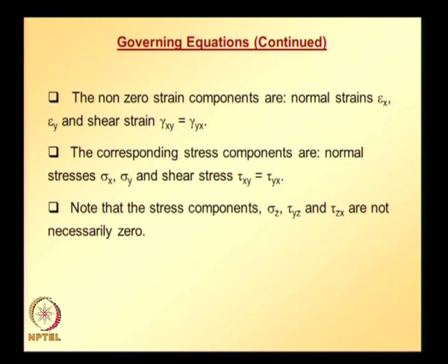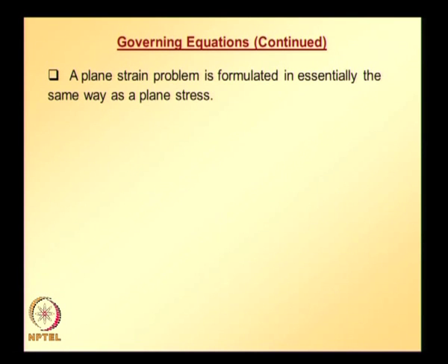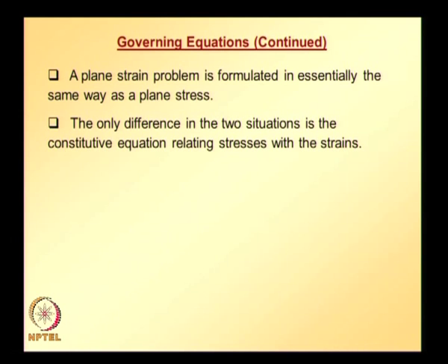And the plane strain problem is formulated essentially the same way as the plane stress problem that we just looked at. The only difference in the two situations is the constitutive equations relating stresses with strains.